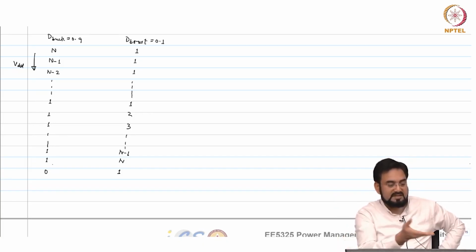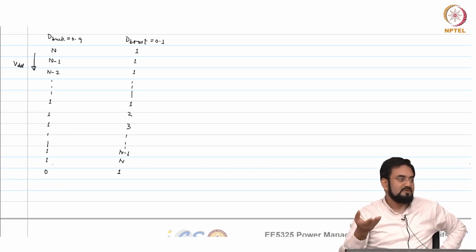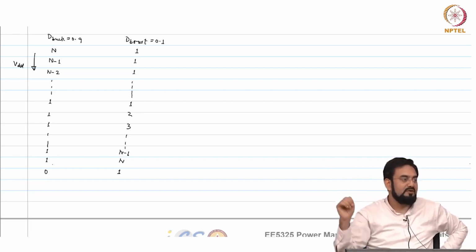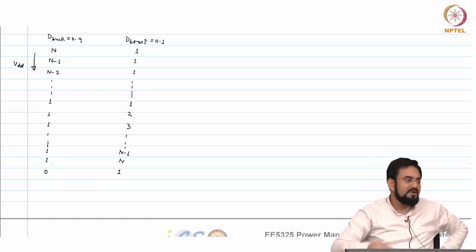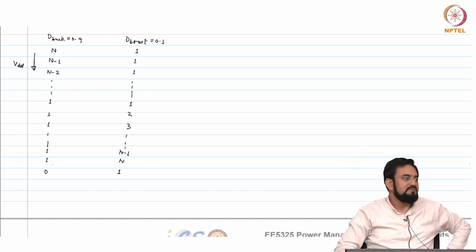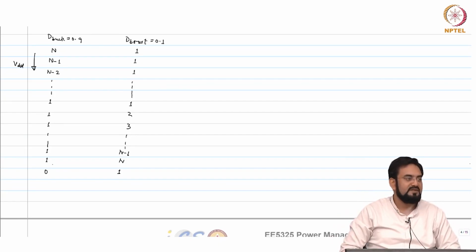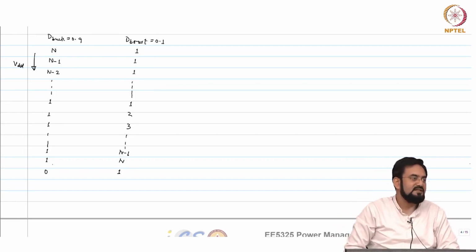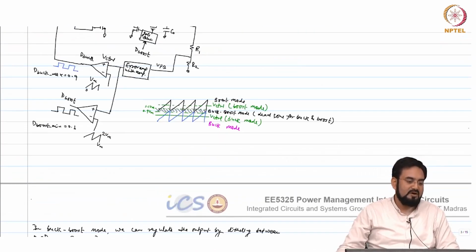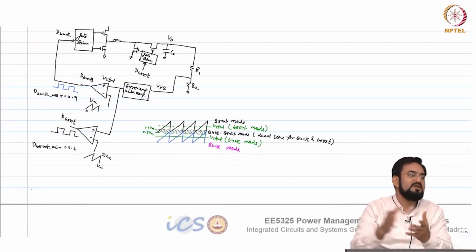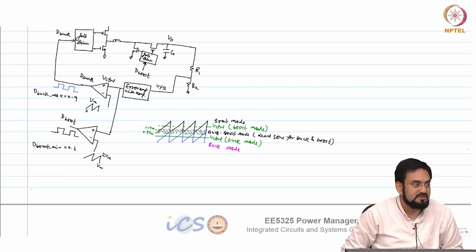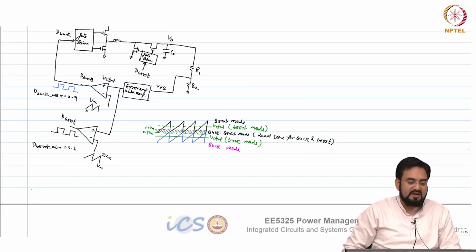I mean, this transition may happen during load also. So, let us say you have kept a 5% margin for load, and this transition has also happened. So, it is quite possible your overshoot may go to 10% or so. But if you have enough margin beyond the load where you can handle this transient due to transition, then you can live with it. You do not have to do anything in that case. Or you have limited your duty cycle very close to 100%, 98% or so, even then maybe you will not get that transient.